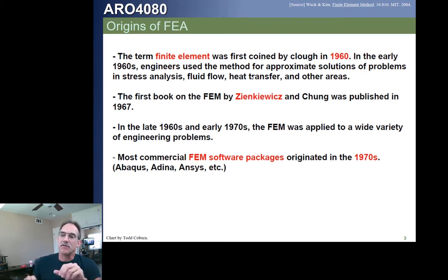So there are a bunch of finite element model software packages. SolidWorks has its own. A lot of the CAD software for drawing structures have their own. A lot of times that software is inferior. It may be really easy to use, but it's inferior to the ones that have led the charge, like the NASTRANs, some of them specialty ones like the Abaqus, and some others.